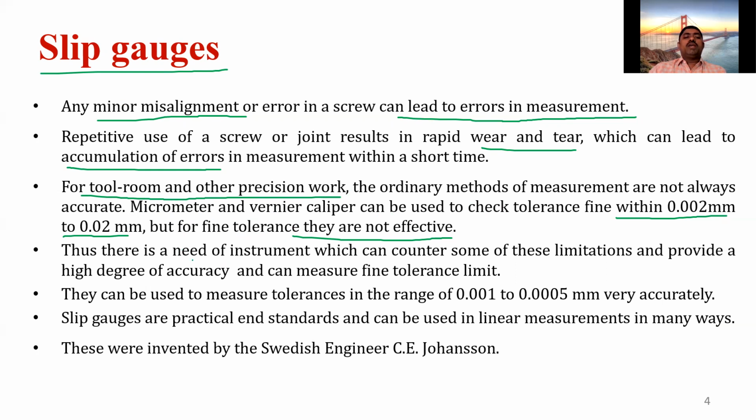So we require an instrument which can counter these limitations, provide a high degree of accuracy, and measure very fine tolerance elements up to 0.01, 0.001, 0.0005 mm. This can be achieved with the help of slip gauges. These slip gauges are practical end standards and can be used in linear measurements in many ways.